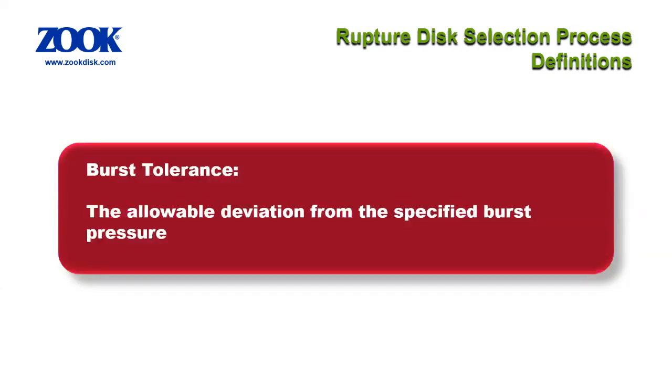Burst tolerance is the allowable deviation from the nominal burst pressure of the disk. All rupture disks are specified with a burst tolerance. The disk is completely dependent on the absolute properties of the material of manufacture, which has an impact on the burst pressure. This is reflected in the burst tolerance, which allows for these inconsistencies. Tolerance can be made tighter. There are extra testing costs for the maker to achieve a tighter tolerance, and it comes at a higher cost also.